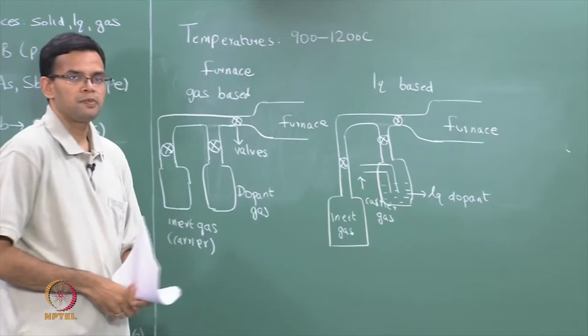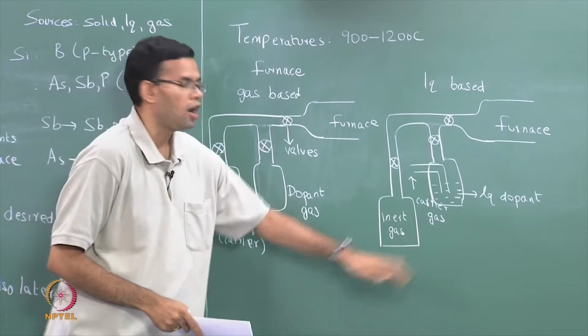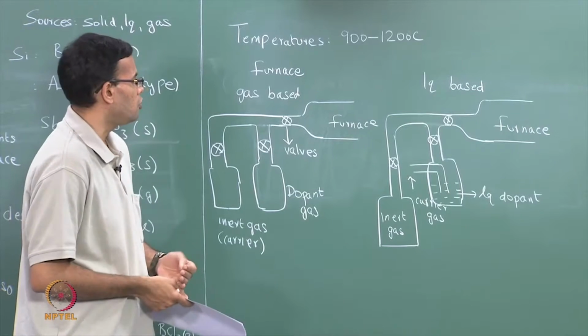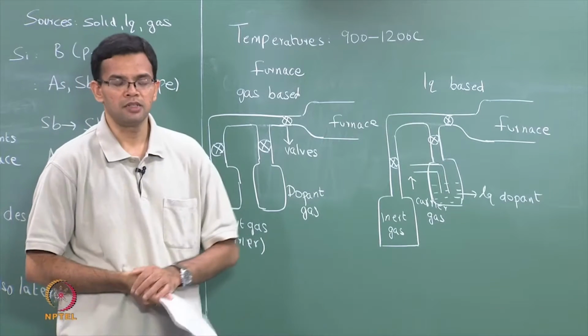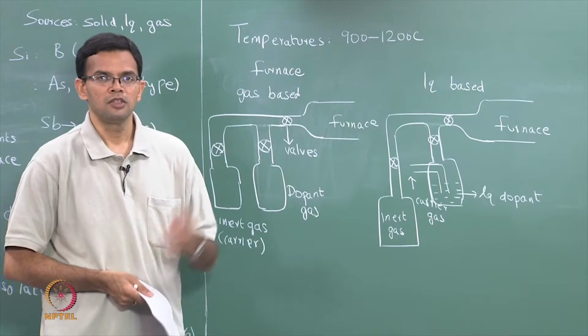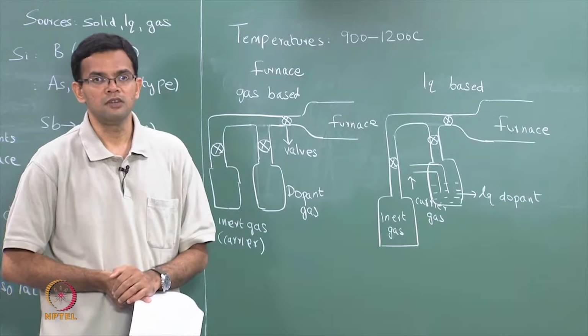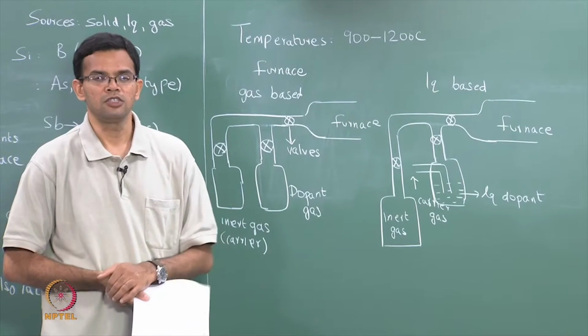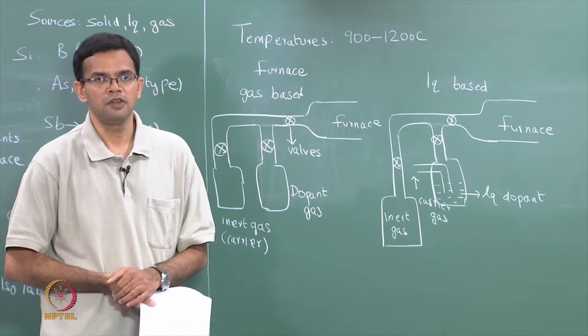The furnace setup is similar, it is just how the dopant is introduced that is different. In the case of both the gas based and the liquid based dopants, the concentration of dopants at the surface is essentially a constant, which will in turn affect the concentration profile within the wafer.